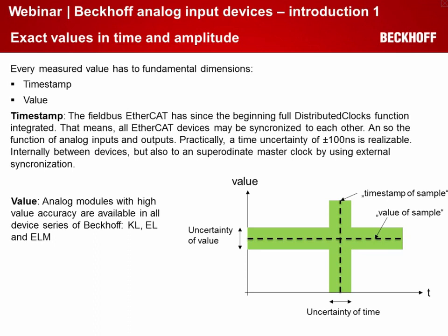In EtherCAT this is very well fixed with distributed clocks, because from slave to slave and from slave to master to the IPC, there is a distributed clock function, the synchronization technology available, and this gives the slaves the ability to run in time up to a jitter lower than 100 nanoseconds in input and in output area.